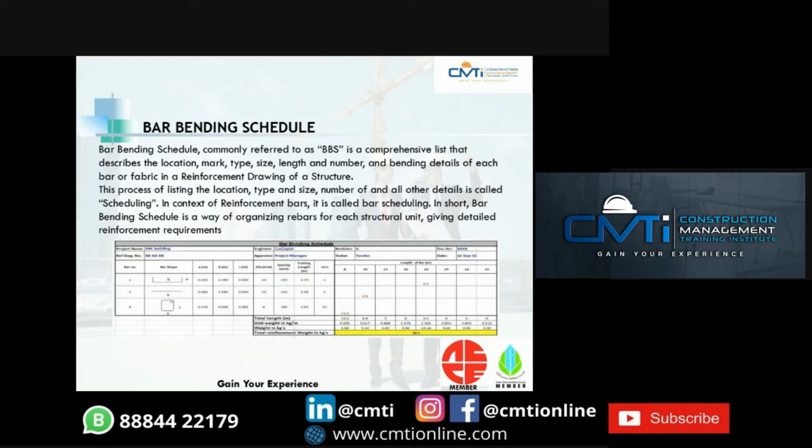The process of listing the location, type, size, number and other details is called scheduling. In the context of reinforcement bars, it is called a bar bending schedule. In short, a bar bending schedule is a way of organizing rebars for each structural unit, giving detailed reinforcement requirements. Below is an example of a bar bending schedule. There you can see the project name, the drawing number, the bar number, the bar shape, its length, its diameter, the spacing, the cutting length, and how many bars are required.